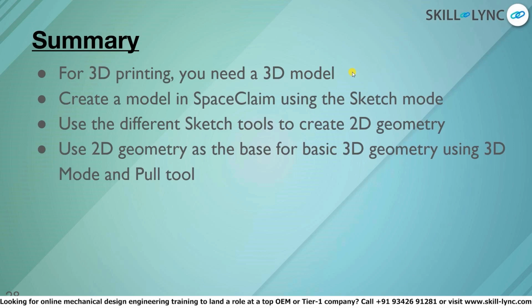In summary, what we have covered in this lesson for week 1 is what is 3D printing, what you need to get started with 3D printing, which is a 3D model, how to get started in Ansys SpaceClaim, creating your 2D model from a 2D sketch, creating that 2D sketch itself, all the different tools and techniques that you can use to get started with your 2D sketches, and how to turn those 2D sketches into 3D geometry using the Pull tool and the Revolve tool.